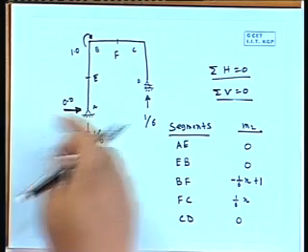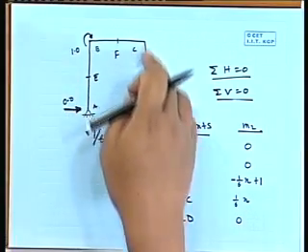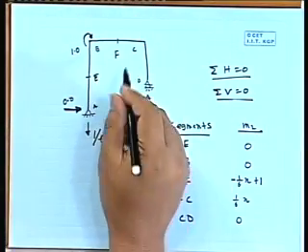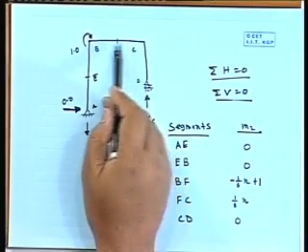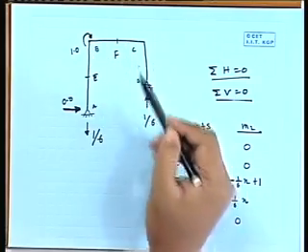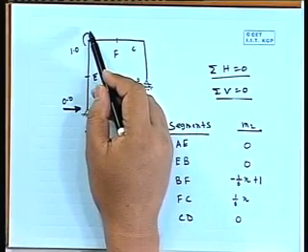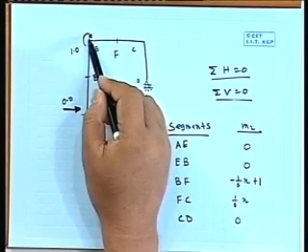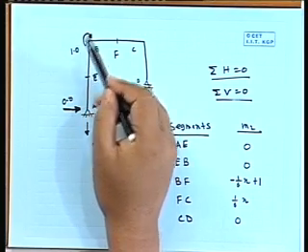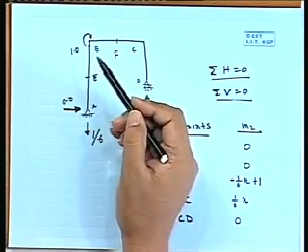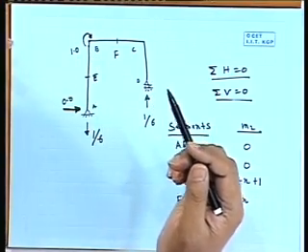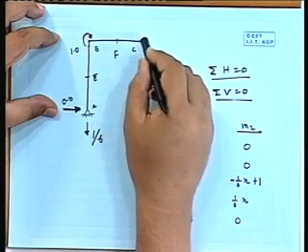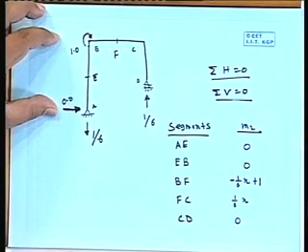Okay. So the entire member, it is 0. Here it is 1 into 6 into x. So if you increase x, when x is 6, 1 by 6 into 6 will be 1, and if you cross that, this will cancel. If you just come below, the moment will be 0, meaning it will be consumed there. So if we draw the bending moment diagram, it will be something like this, a triangle.